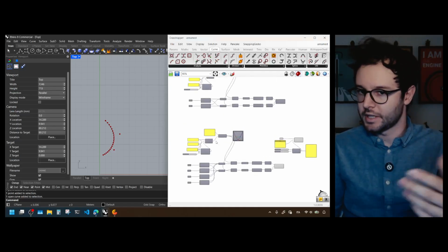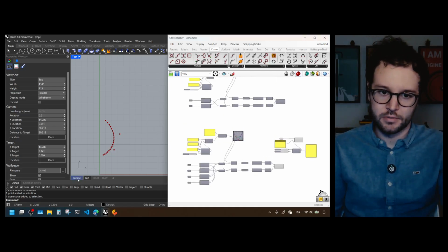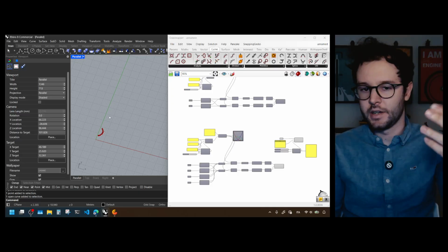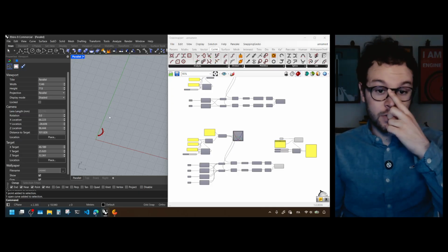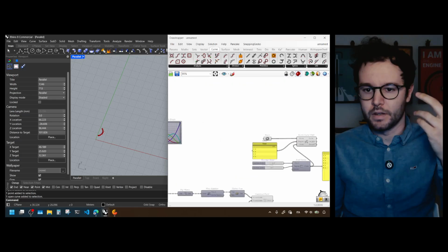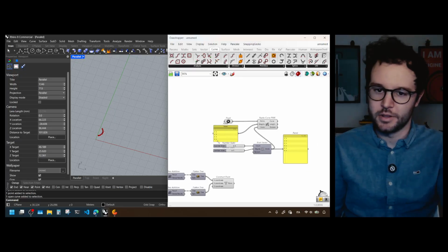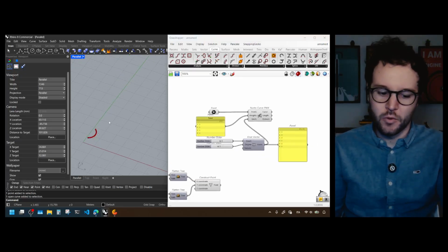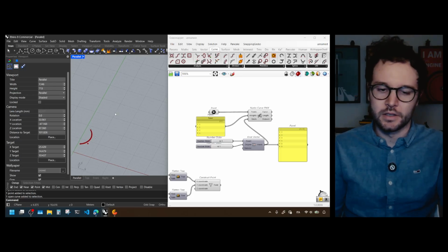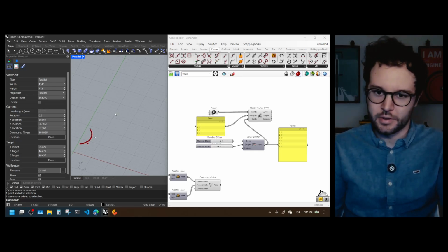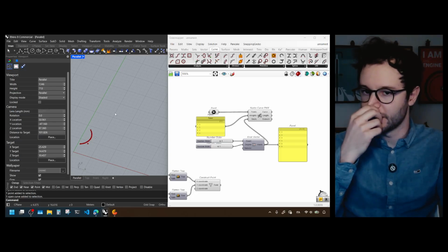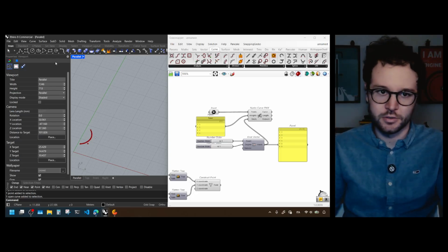We're not going to go in the same detail, but I'll just show you in Rhino directly this concept of the surface, because now that you understand control points, degrees, the weights and the knots, you can easily extend with your mind how it may work in 3D, and you don't need to exactly know the math behind it. By knowing these parameters, you can already control very well the NURBS, also the NURBS surface.